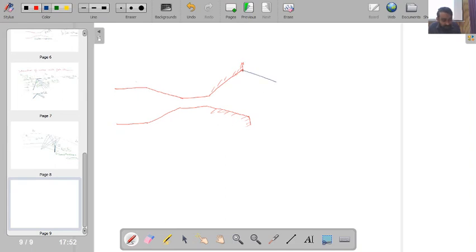Here I will be having one shock wave. Here also I will have one shock wave. These two will meet at this point and then will further refract and move ahead. Then I will be finding, at some point far away, I am having pressure equal to P infinity. So say this is the point where I have got pressure now equal to P infinity.